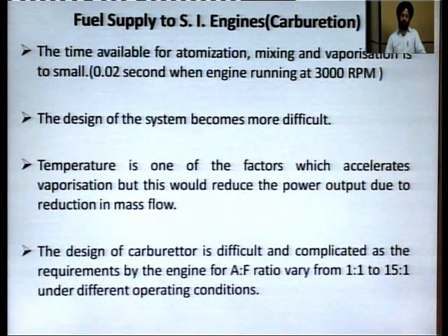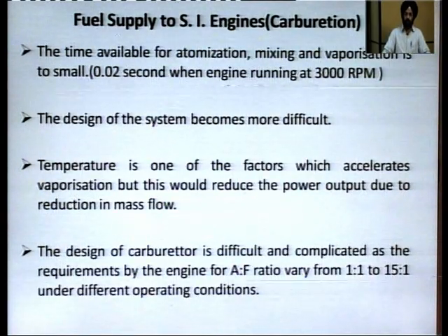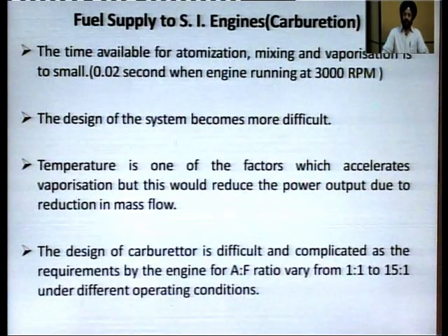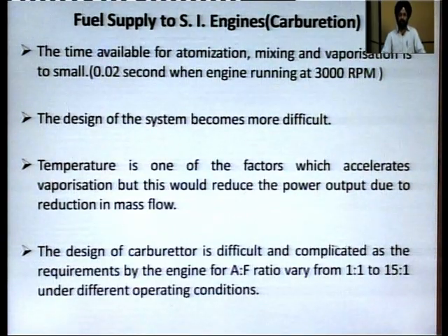Temperature is one of the main factors which accelerates vaporization, but it will reduce the power output due to the reduction of mass flow. As the fuel is heated up, its mass flow will reduce and that will reduce the power output. So, we have to take care of this. The design of a carburetor is difficult and complicated because of the requirements of the engine. The engine is not running at a constant speed.